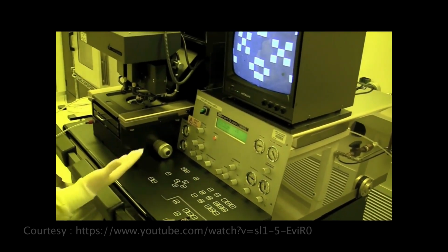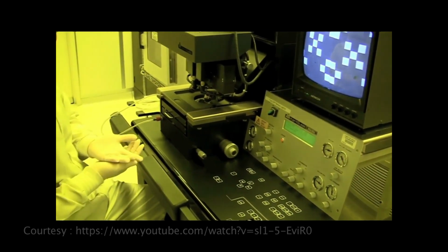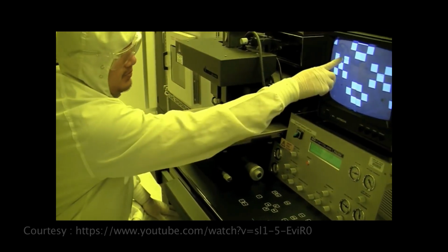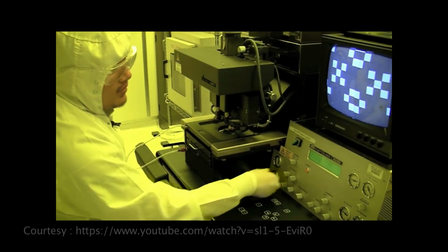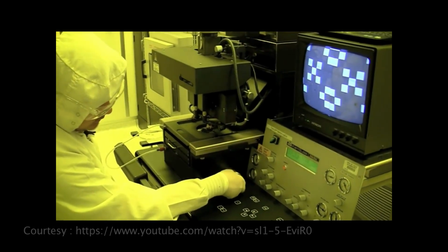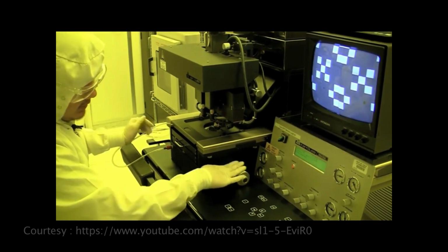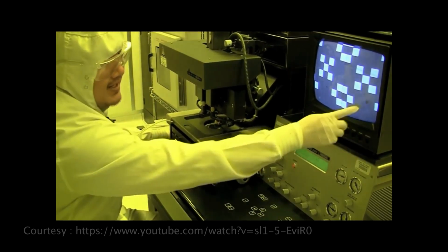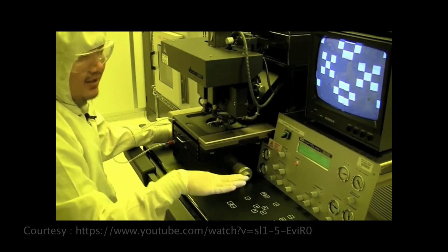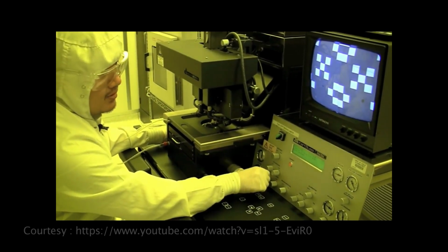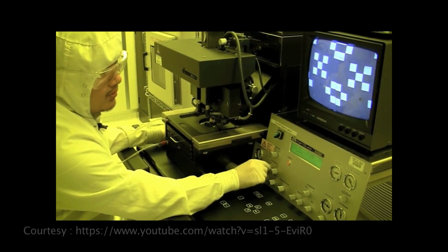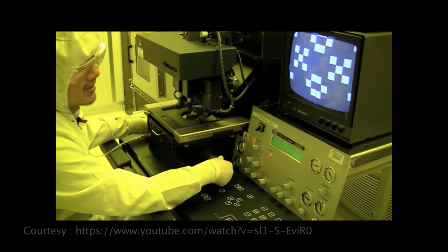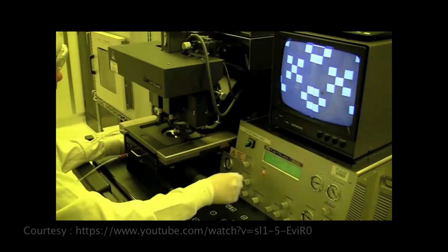So what you would do is similar to backside alignment. You would align your alignment marks on your wafer to these right here. So you can see that if I move this, these knobs always control the substrate. So when I move this, you can see that this has moved. So you can tell that's the actual substrate moving, not the mask. So you try to focus it, and you're trying to find your alignment marks and align them to the features.